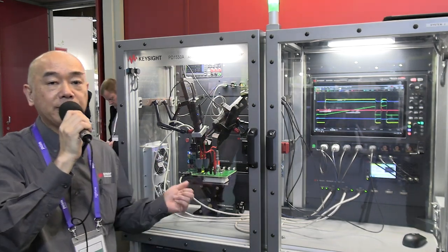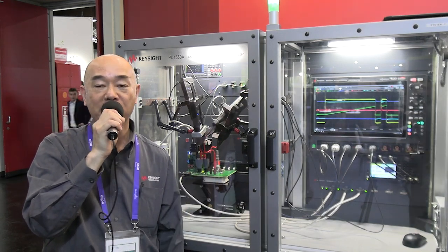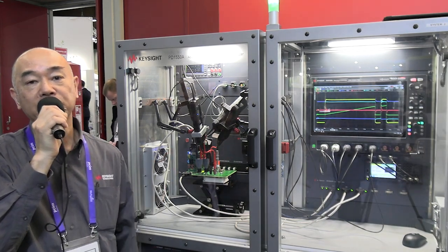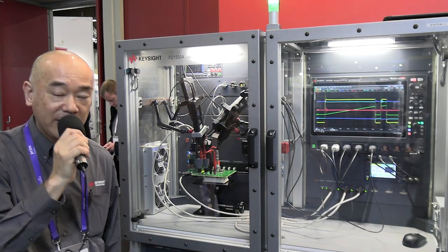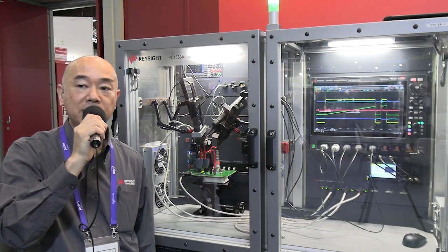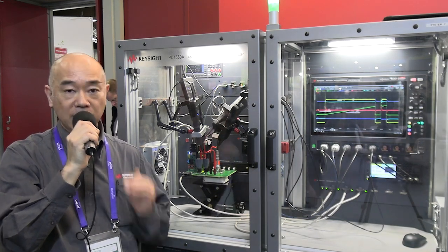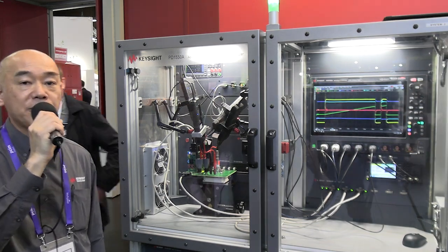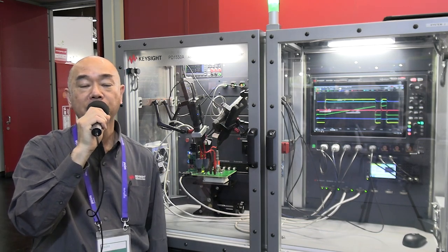We do use the shunt resistor to have a higher bandwidth of the sensor, which goes up to a few hundred megahertz, which is sufficient for characterizing the wide-bandgap devices. And also for that one, we use the RF compensation to make the current accurate and consistent. The system goes up to 1,000 amps for sourcing and 2,000 amps for measurement. And also the voltage can go up to 1.36 kV.